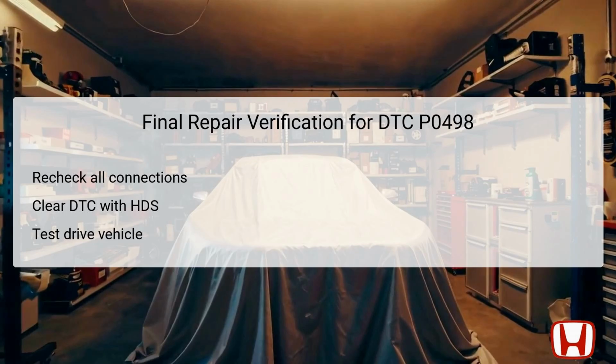Once the DTCs are cleared, conduct a series of road tests to ensure that the vehicle operates normally and that no further DTC P0498 codes reappear. Keep an eye out for improved fuel economy and ensure that the check engine light remains off after driving under various conditions. This ensures that repairs are effective and the system is functioning as intended.